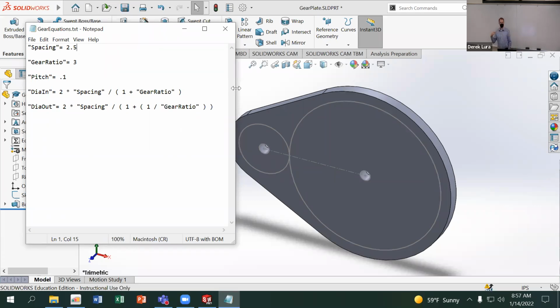Now, this functionality would be kind of limited to exporting to the part, except for the fact that now I can use this file in other parts. So if you had, you know, a V8 engine, where there's hundreds of parts that are all basically driven by the same parameters, this can be really helpful from a design standpoint because you don't have to open and edit 100 parts to make a change in the design, right? And as long as you're careful about how you build the parts, that can be fairly robust. You can't have a lot of errors with that.